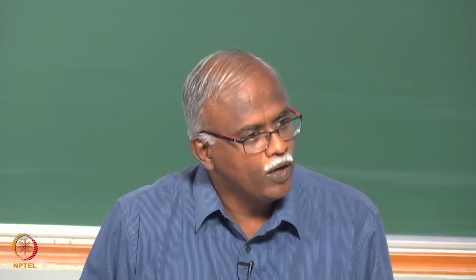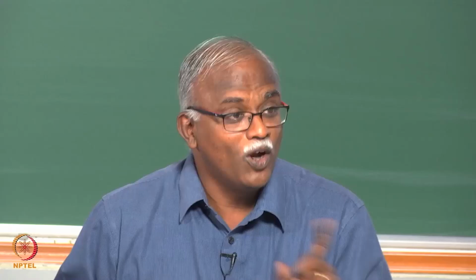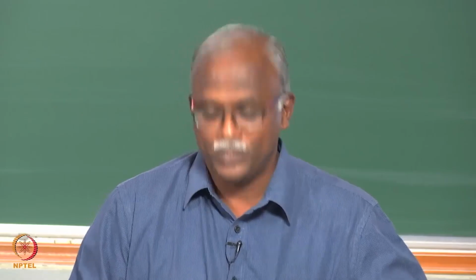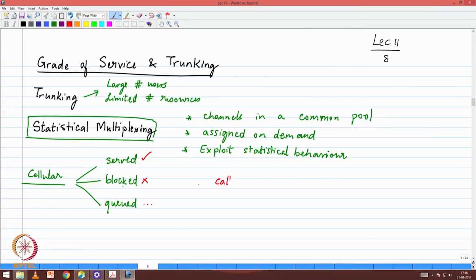Blocking. But what about call waiting? Isn't that what queuing is supposed to be? Think about it. But resources have been allocated to that user. Excellent point. The resource has already been given to you, so basically you are not blocked. The only reason the call did not complete is because the user was not available. So call waiting is not a queuing system. Call waiting is not the same as queuing. Okay, the system that we have for cellular is a system that will block. If it does not have resources, it will block the user. Okay. Keep that picture in mind.